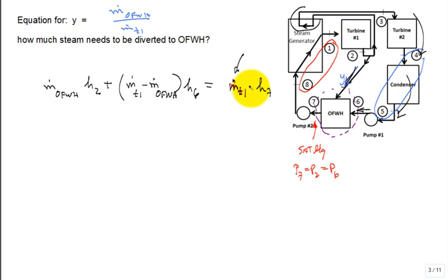Professor, isn't there a lot of heat transfer in this heat exchanger known as the open feed water heater? But it's internal to our control volume. That's why a lot of times we're very careful. We say, this is our control volume, and nothing goes across that boundary in the way of heat transfer to the surroundings. There's heat transfer inside the control volume, but not to the surroundings across it.